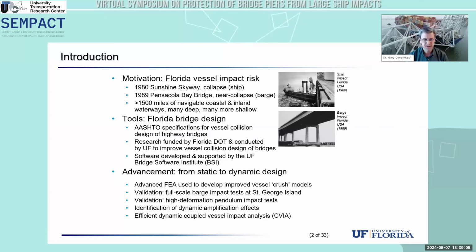So some of the tools that we use in the state of Florida for bridge design include obviously the AASHTO provisions for vessel collision design of highway bridges. They include results from research that's been funded, again, over many years, 25, 30 years at least, by the Florida Department of Transportation and conducted here at the University of Florida. And also, I'll point out that we at the University of Florida have the Bridge Software Institute, where we produce software which is used by engineers to assess bridge vulnerability to vessel collision. And so those are among some of the tools that are used for bridge design here in Florida.